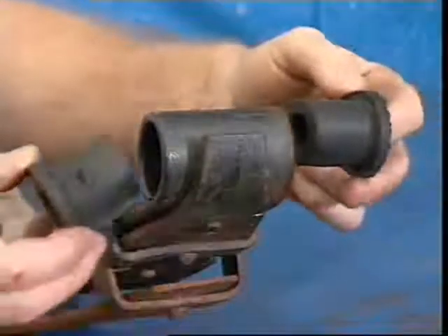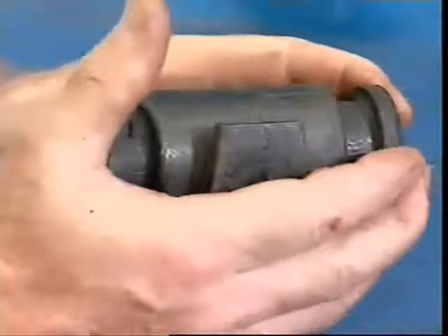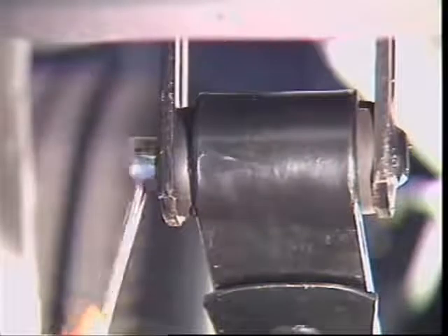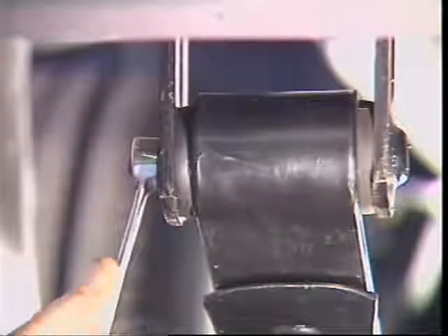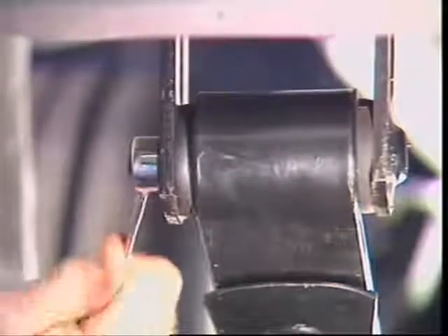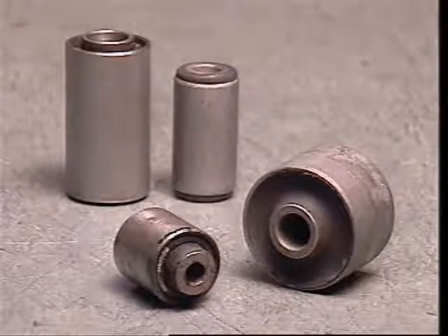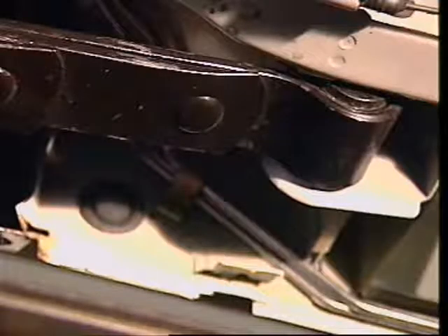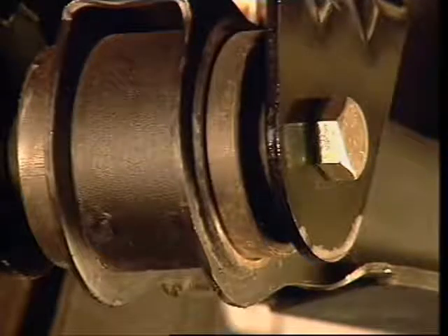Spring shackle bushes can be molded to form two halves to fit into each side of the spring eye on the swinging shackle. With the spring loaded and the shackle plates tightened, the rubber is compressed in the eye and at the face of the plates. As the spring deflects, the rubber shears without tearing. Metallastic or rubber bonded bushes are normally used for the front eye of the spring at the fixed shackle point, and also in control arm applications.